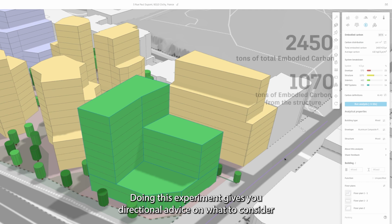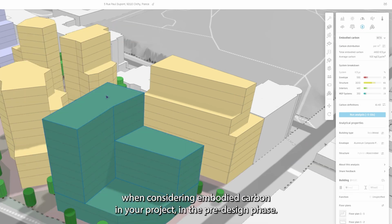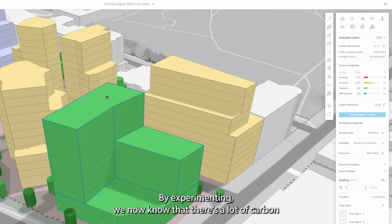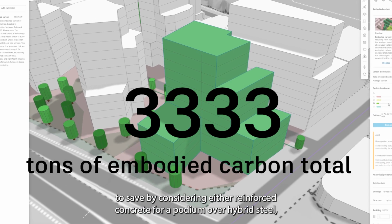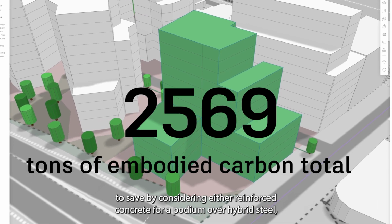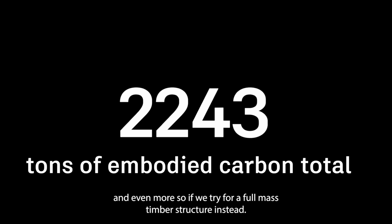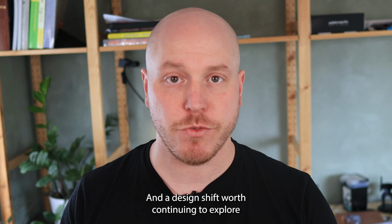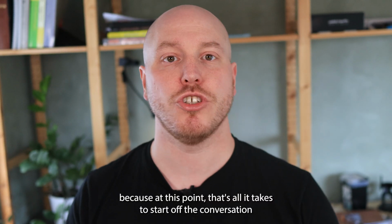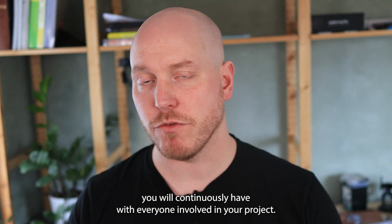Doing this experiment gives you directional advice on what to consider when considering embodied carbon in your project in the pre-design phase. By experimenting, we now know that there's a lot of carbon to save by considering reinforced concrete for a podium over hybrid steel, and even more so if we try for a full mass timber structure instead. And that's an effort worth making and a design shift worth continuing to explore. Because at this point, that's all it takes to start off the conversation you will continuously have with everyone involved in your project.